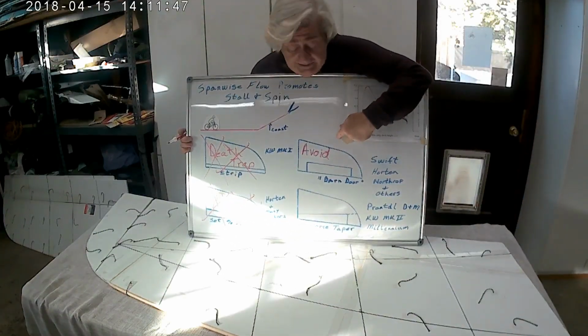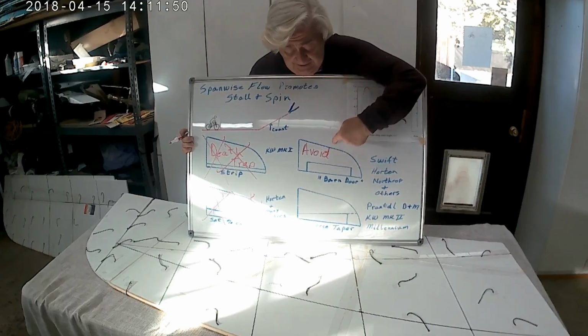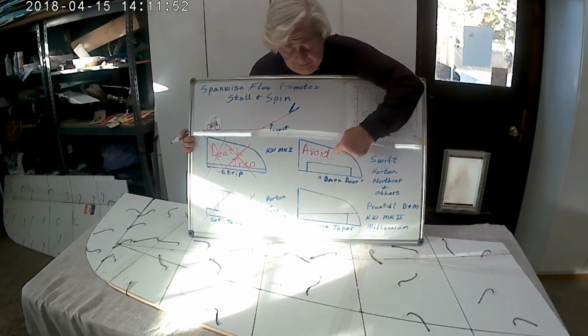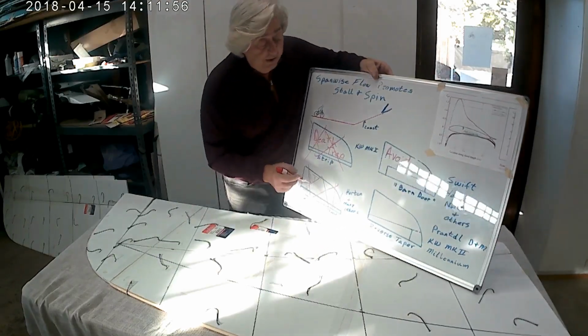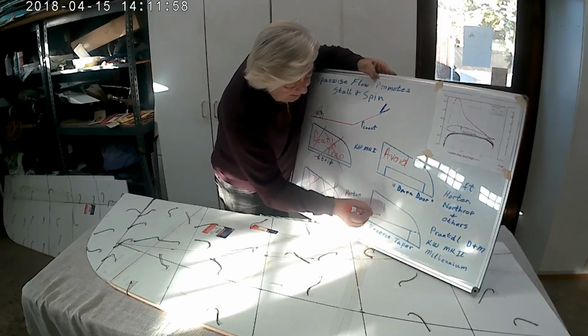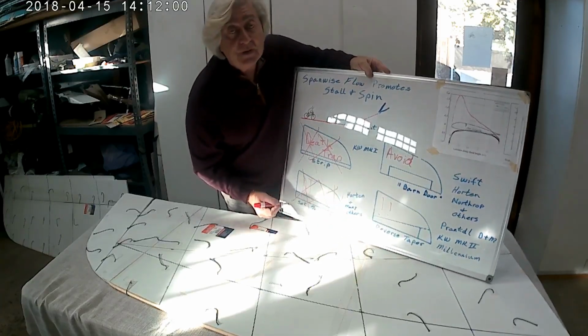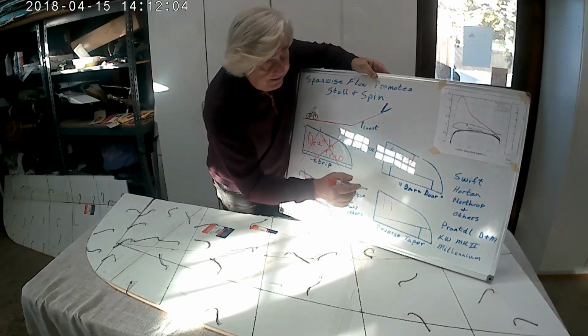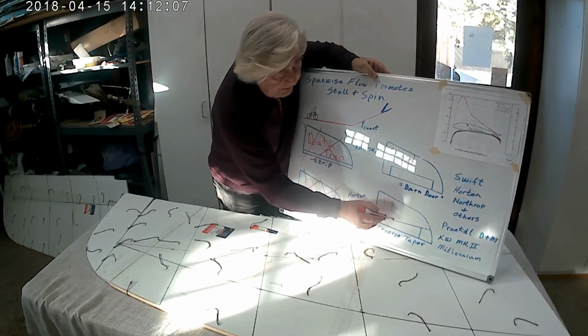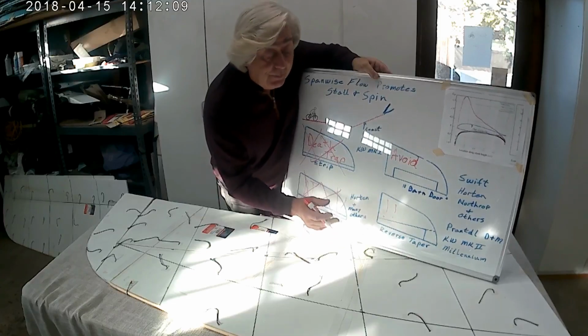Avoid them if you can. If you have a choice, avoid the barn door elevon. So, our best answer, our winner, is the reverse taper elevon, because of the three factors, this really helps keep the flow attached. Now, how much reverse taper?